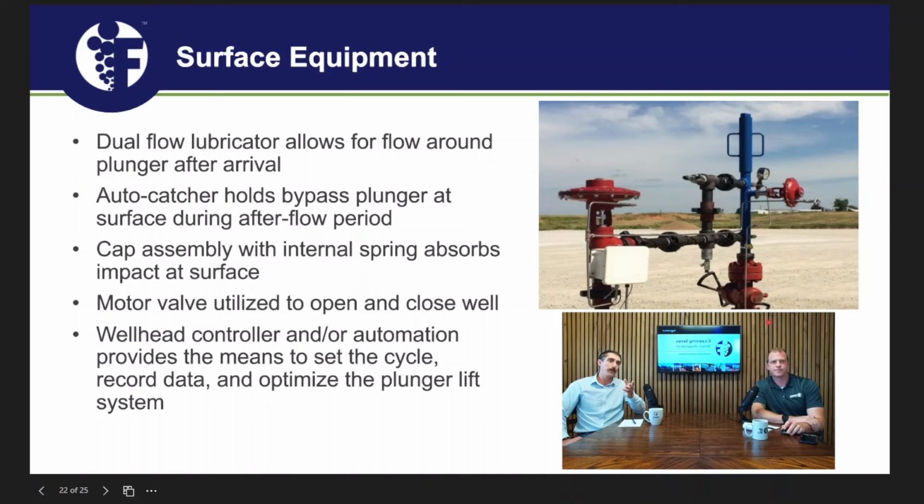So here you see we've got the lubricator, which is this blue thing here, and it's attached straight to the top of the wellhead. The one pictured looks like it's about a 3K operating pressure, so that's a low pressure lubricator. We have 5K, 10K, and you typically match those to the wellhead, whatever the operator requests, because obviously you've got higher costs with higher pressure ratings.